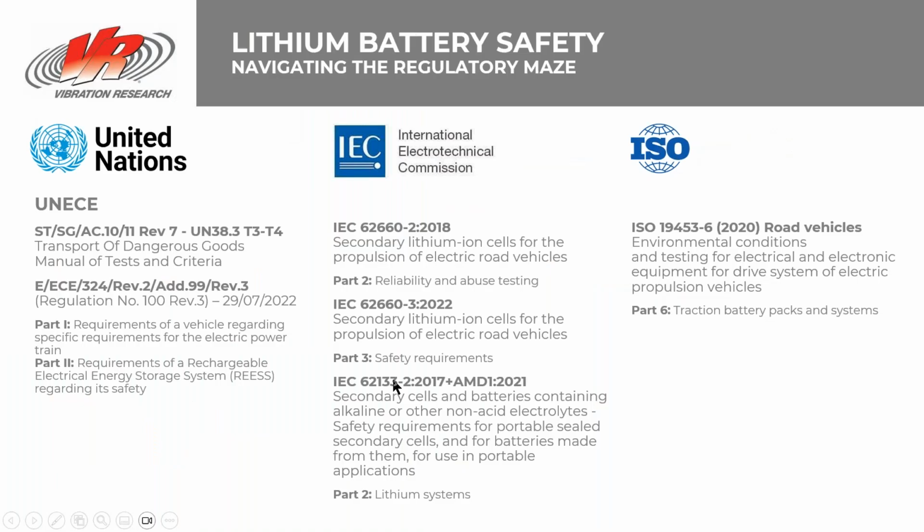Here's a quick look at test standards associated with lithium-ion battery packs. You've got the United Nations, the UN 38.3 United Nations standard. This is for the transport of dangerous goods. So the level of vibration and shock testing within that specification should really be aimed at anything that's being packaged and transported around.